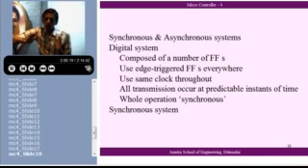So wherever possible, we work with a synchronous digital system. We don't work with an asynchronous digital system. As the system size increases, definitely work with only a synchronous digital system. With an asynchronous digital system, that indecision can create a lot of problems because as you increase the size, you don't know whether you have got a proper output at this time, and so on.